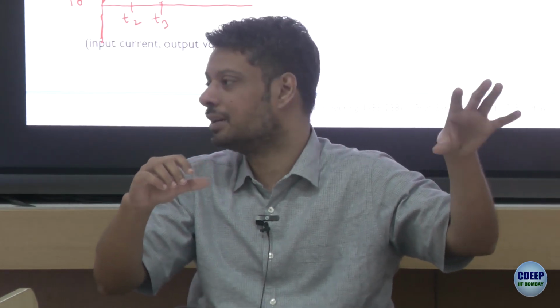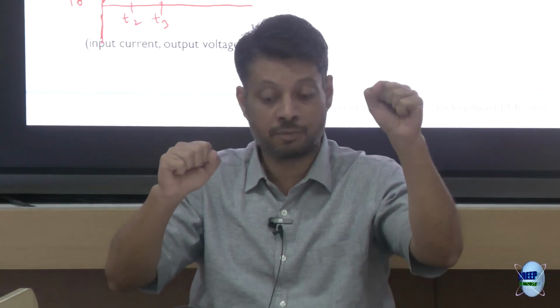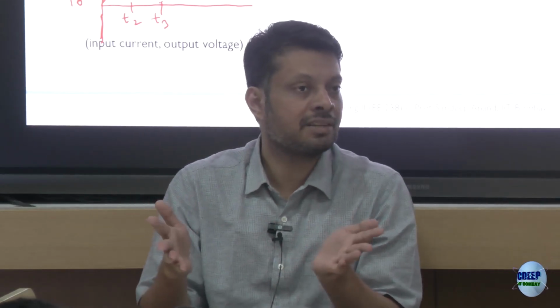And now with a small voltage source, 20 volt, 30 volt, 100 volt, doesn't really matter compared to this infinity, right? And you see the anode has become, because of Kirchhoff's voltage law, at a very high potential with respect to the cathode. So the diode will still conduct, right? Actually it will not become infinity, but it's just a way for us to understand that we assume hypothetically it stops and we realize, oh, it cannot, because the potential will become infinity.